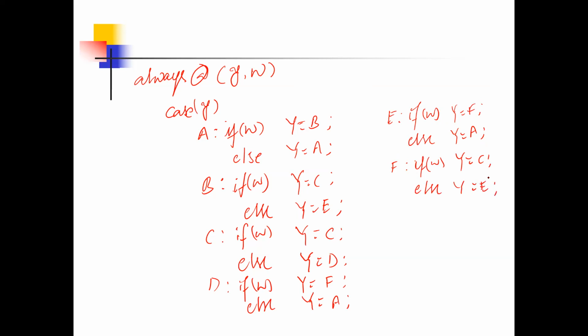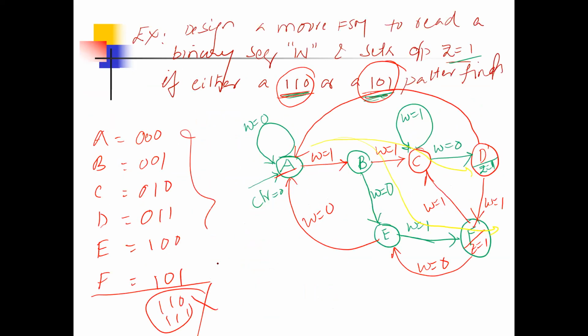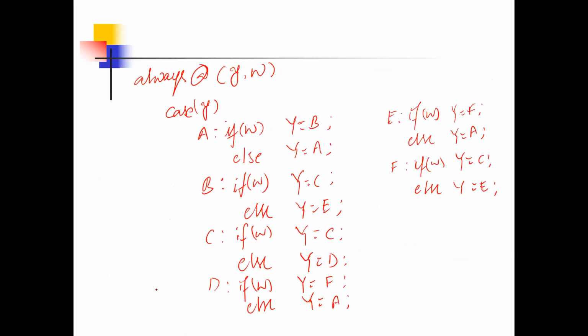Yeah, all states are over, but out of 8 combinations, we used only 6 combinations, the remaining 2 combinations are not used, so a default case is required here. So I will write here default. What is the default? Y is equal to 3 bits of X, you can make it. Yes. Now we started with case, so it must be ended with the keyword endcase.